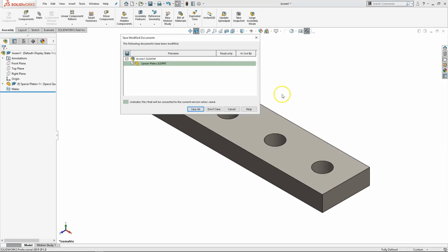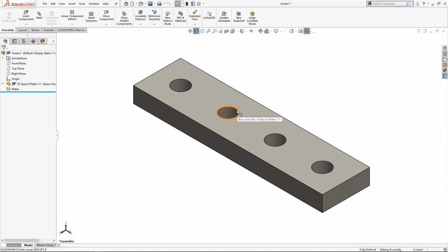So as you build these parts out, and then it comes into the assembly, there are a couple of tricks that I throw in there if you want to utilize the mate references. If you are going to be inserting a lot of pegs, pins, or geometry, you probably won't want to go through one by one and say this is coincident, this is concentric, this is whatever. And that's where you would go into the part.